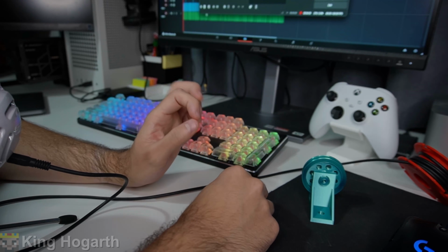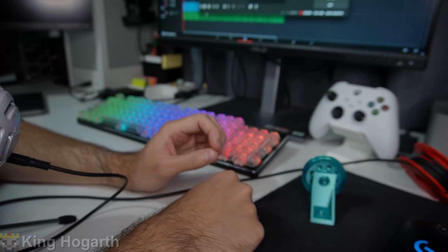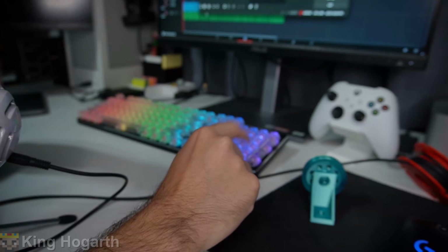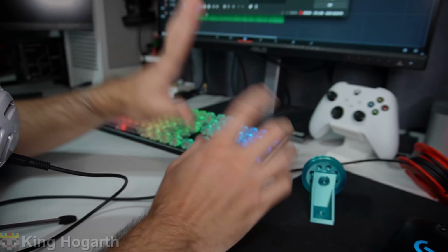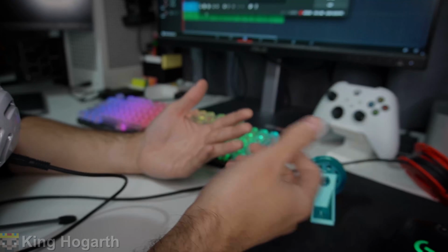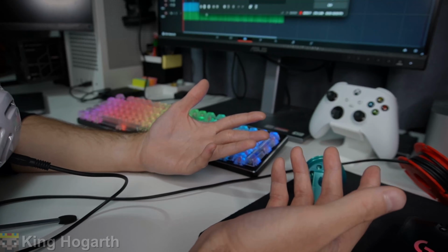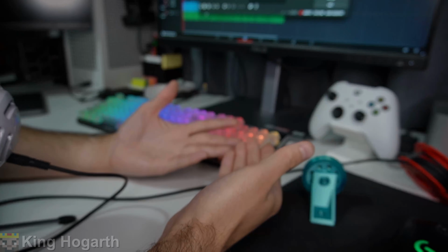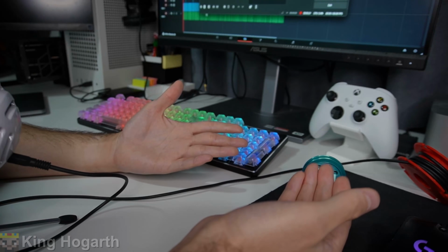When I was dimensioning the holes for the wheel here, and it created an angle mate. And I zoomed into the spot where that happened, and I noticed I clicked the line just because the point was really small. But there's a simple solution for that. Just go into the configuration, change the point size.